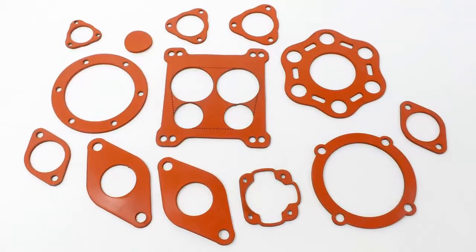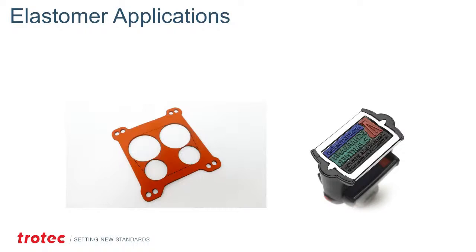Once they're pulled out of the machine, you definitely need to wipe the edges because they have a little of that carbon buildup on them. But once they're wiped off, you get that molded, clean, finished look on the rubber. It's a great material to work with, but again, as you saw in that video, it is dirty material to work with as well. Most of your cutting applications, spacers, gaskets, and rubber stamps, are the primary applications for this material. If you need to cut it for anything, the laser is a great alternative tool for processing it.